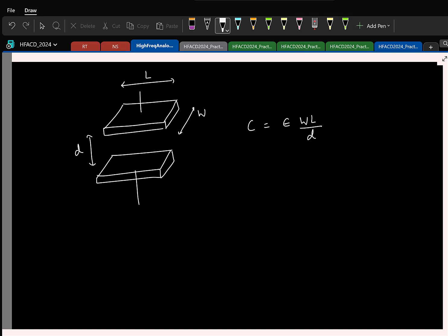By the spacing d. Again, as I mentioned, this vertical spacing is not under your control. So if I take all those things that are not under your control separately, we'll have something like this. And this is typically called the unit capacitance, which tells the capacitance per unit area of this particular structure. And again, this number can range anywhere from 1 femtofarad to 10 femtofarad per micrometer square.